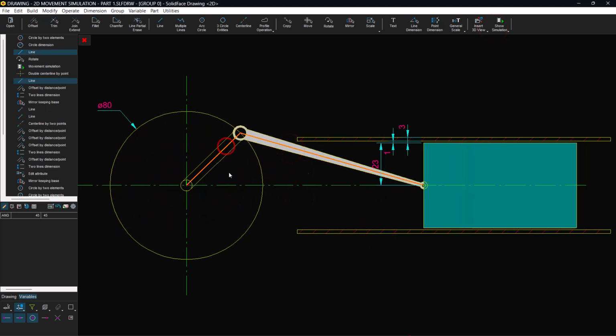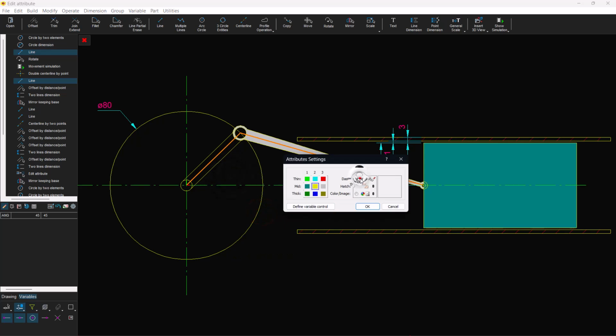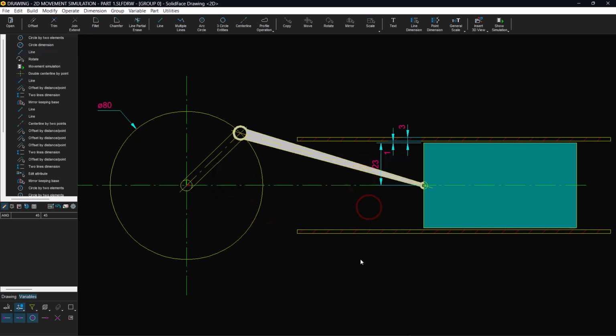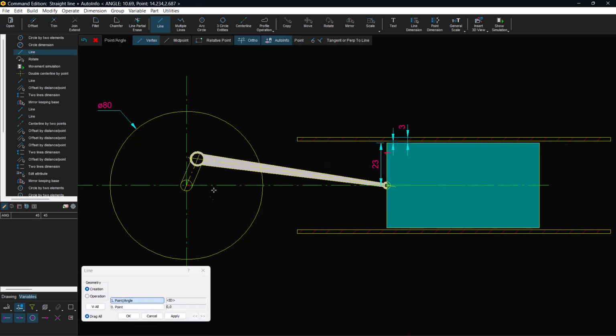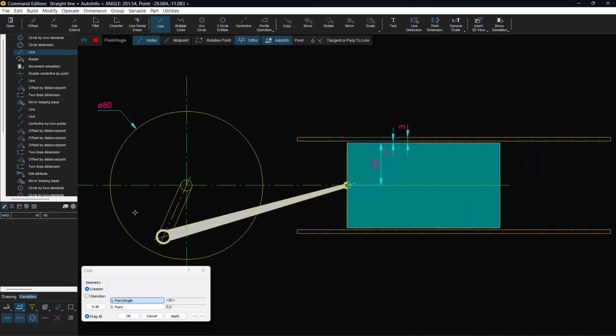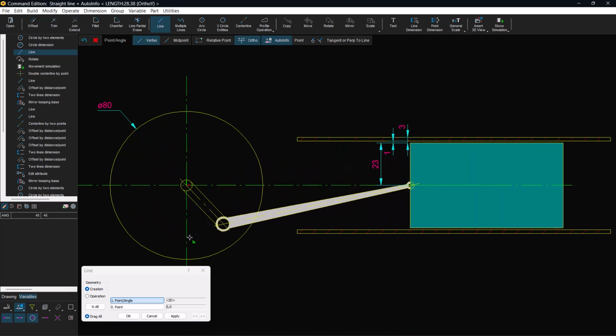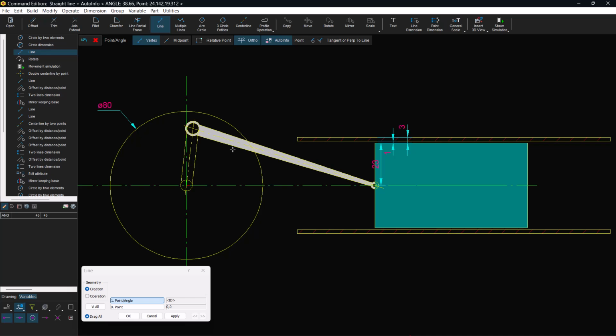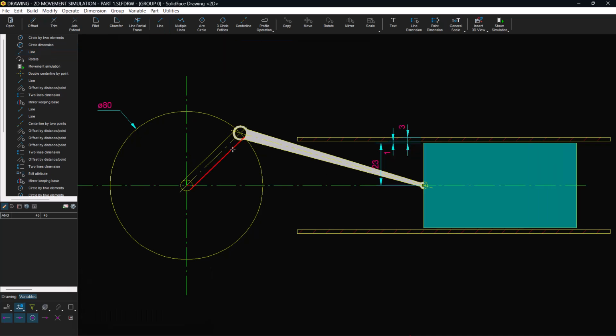It is important to test the simulation during each phase of the process. One simple way to simulate the simple movement is to click on the base element that controls the simulation and test it by dragging the line. If any errors occur, you can edit the geometry directly on the graphics screen and then build a new geometry. But in parametric or simulation constructions, if it is necessary to rebuild the geometry, avoid deleting them through their selection in the graphics area. That is, avoid the erasure and then construction of new geometries.